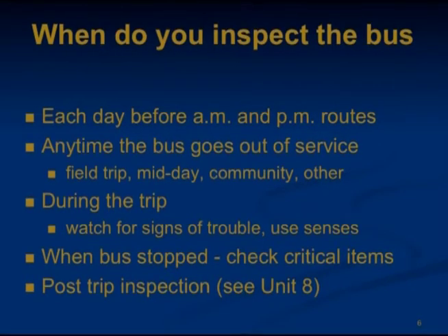Look at your steering. Is it responsive? Is there too much play or jerking? Is the power steering quiet? And for suspension, look for sagging or excessive bounce or bottoming out going over bumps, excessive swaying when turning or cornering. Report any unusual ride or handling characteristics. The cause could be faulty shock absorbers or broken springs.